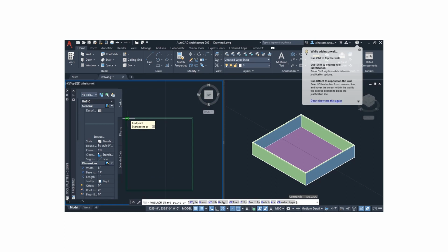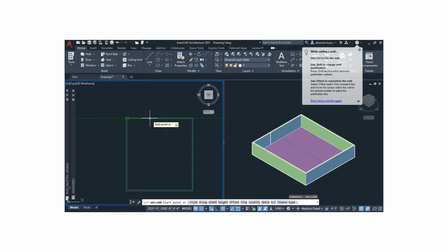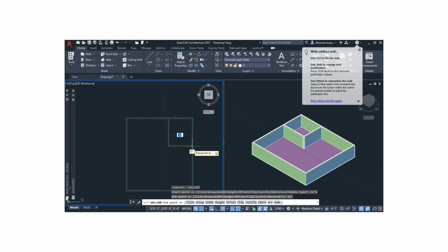we snap here, you will see a snapping point and a trace showing that you have snapped this point. You actually want to draw a wall, but you want to start not at this point but at some distance from this point you've just snapped. So you're telling the software that you want to start at 32 feet 6 inches away from that wall. So if you hit enter, you start drawing from a distance of 32 feet 6 inches. So you bring the cursor down, and the distance there is 22 feet. So we enter 22 feet. So move this and close it to this wall.